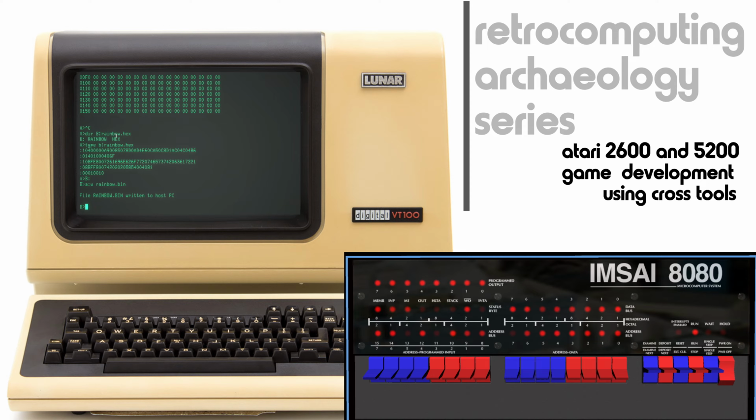As I read through what's been reverse engineered on the hardware, we've got sprite registers, just like on the Atari. We've got 4 of them, just like on the Atari, and all the missiles can be combined together to make a 5th player, that sort of thing. Let's see if the knowledge that I have on my Atari work actually translates over into the 5200. Write a little program.